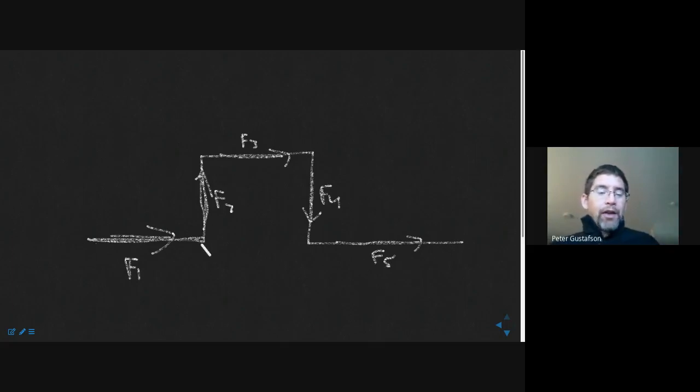And we can now calculate what the magnitudes of those forces are, because what we know is the force per unit length, and now we can integrate along the length. One other thing that we recognize, the original force, which was Sy down here, has to be equal to the sum of all of these other forces.